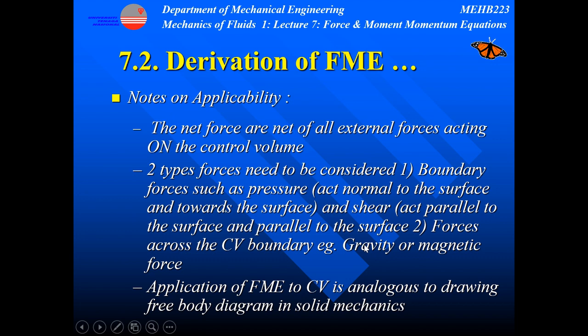Alright, the application of the force and momentum equation, or linear momentum equation, to the control volume is analogous to drawing the free body diagram in solid mechanics. So before you answer the question, you have to draw the free body diagram so that you know what forces are acting on the body.